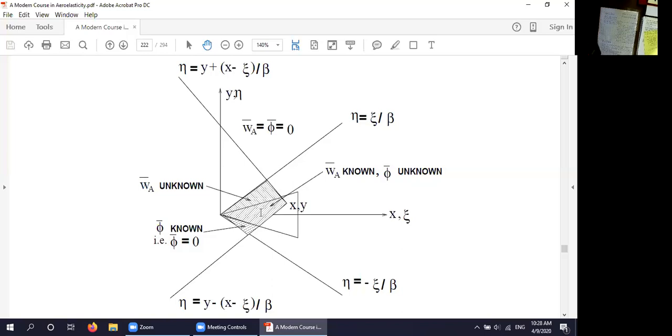So we have 100 unknowns, namely, we either know the d phi dz on the wing and we don't know phi, or we know phi off the wing and we don't know the d phi dz off the wing. But the number of unknowns and the number of boxes and the number of equations that we get by taking that double integral, and dividing it up into little boxes and producing 100 linear equations, one for each box, is just the right amount.